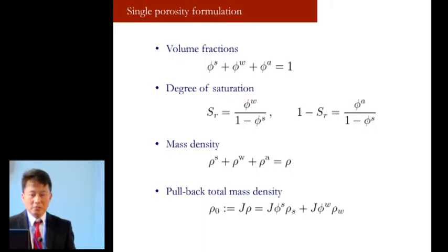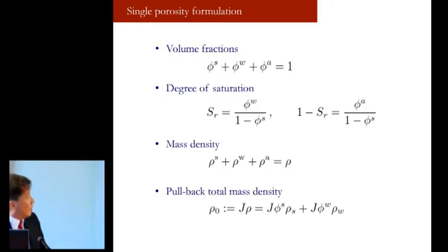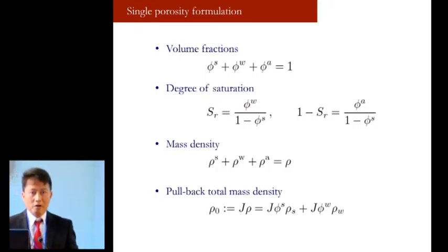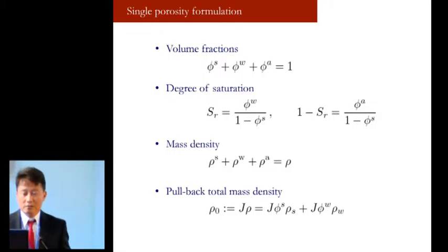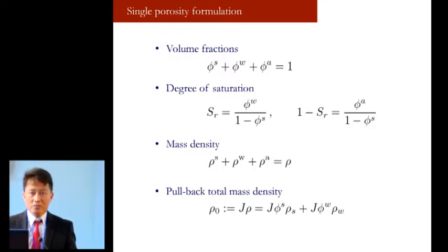Okay, so let me just recall the basic equations for single porosity formulation, and then I'm going to talk about double porosity formulation subsequently. Now, we use theory of mixtures, where volumes can actually be subdivided into a number of phases. In the following discussion, I'm going to consider a solid, water and air mixture, and we have the following definition of volume fractions: phi^s, phi^w, and phi^a, with the superscripts denoting solid, water, and air. And the volume fractions are required to satisfy the closure condition, the sum being equal to 1.